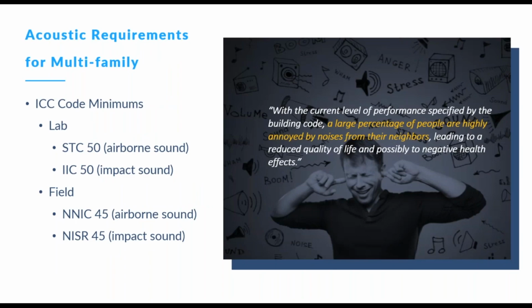Like I said, acoustics basics, we'll start here. We have code minimums for acoustics, and a lot of times that's the driving factor for our need for noise control in a building, especially multifamily. There are other codes for other types of spaces. There are codes or guidelines for designing schools and for hospitals. Government has its own, the GSA, and different government groups have their own. There are acoustics requirements within LEED and WELL and all of these different things. A lot of them use fairly similar terminology and work somewhat similarly to the building code for multifamily.